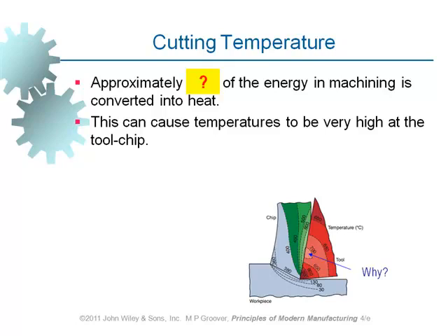There are so many reasons. One of the most important ones: when there is a change of temperature in the workpiece, what happens? It expands, and consequently, what you produce is not what you get. Because of the elevated temperature, the workpiece expands, so you produce something precise, but after some time, what you measure is different.